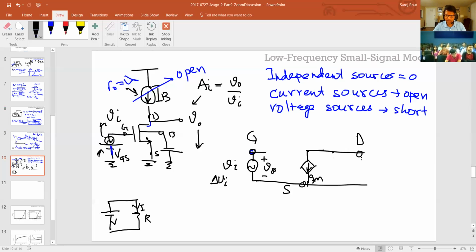So now the question is, we have a drain, another small signal model, GS, which is source to drain current, but the voltage is actually source to bulk, which is multiplied to this. So I should write the whole expression. This is GM times VI, and this is GS times VSB, okay?